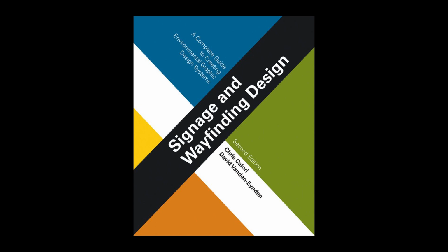Enclose the sign numbers in a distinctive shape that stands out visually from the plan background and any architectural symbols or shapes on it. Another consideration is color coding on final plan drawings. While many organizations are reducing their reliance on paper prints, and while full color printing has become relatively widespread and affordable, some parties that use the signage drawings may still be using paper prints reproduced in black and white. The techniques outlined here don't rely on color to distinguish sign locations and numbers, and therefore result in drawings that are readable when reproduced in either black and white or color.